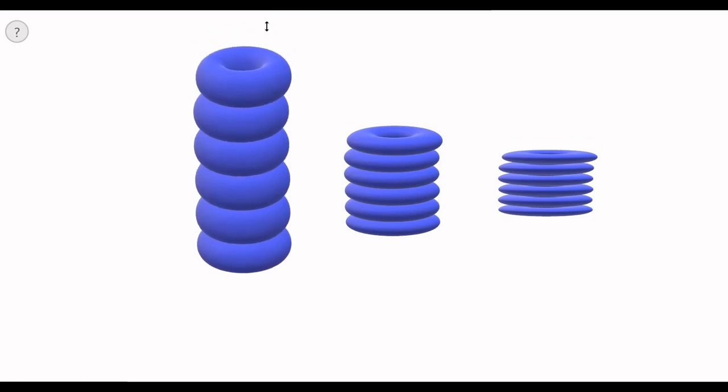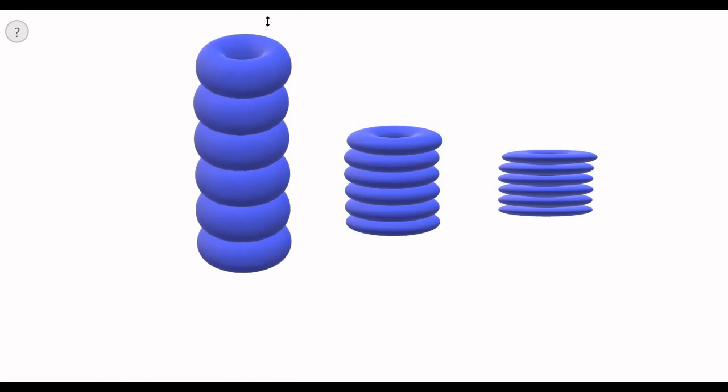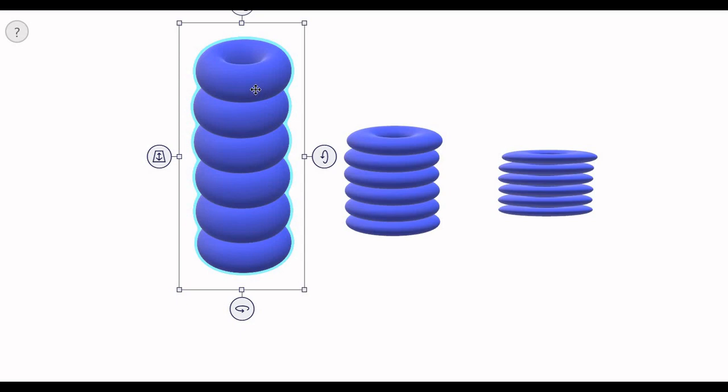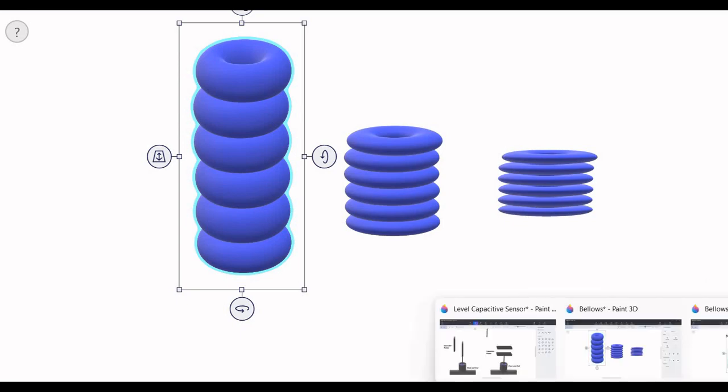So the free end, which is connected to a secondary transducer, produces a voltage or current signal which is proportional to this axial displacement, which is again related to the differential pressure, that is the difference between external and internal pressure. So this measures the liquid column pressure.